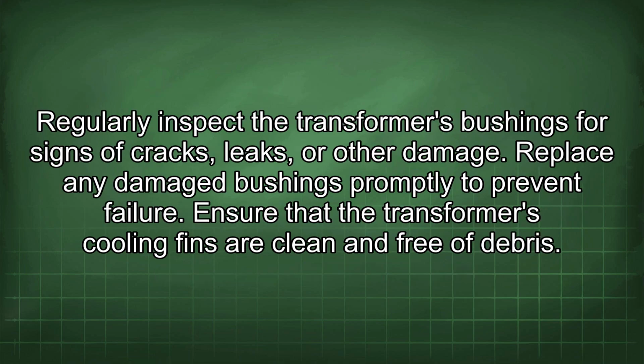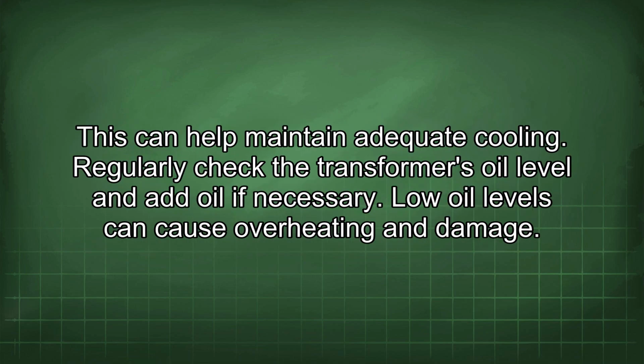Regularly inspect the transformer's bushings for signs of cracks, leaks, or other damage. Replace any damaged bushings promptly to prevent failure. Ensure that the transformer's cooling fins are clean and free of debris. This can help maintain adequate cooling.